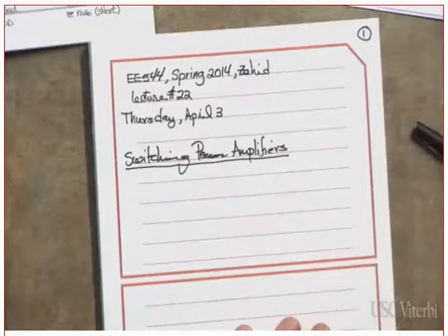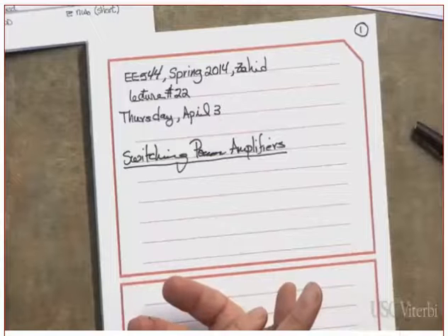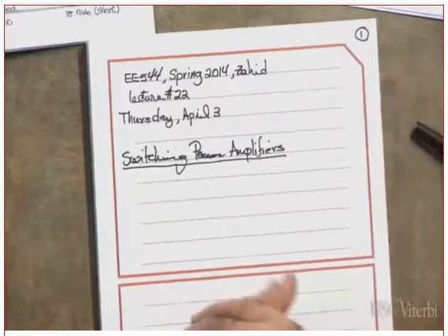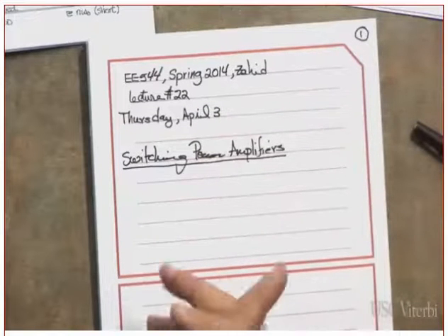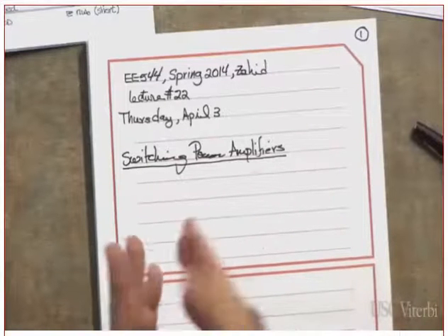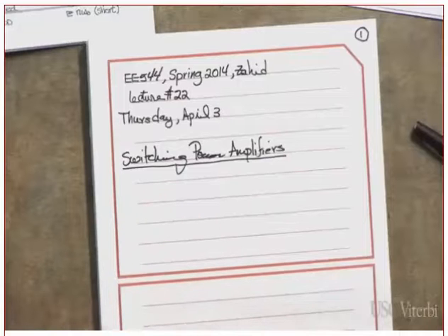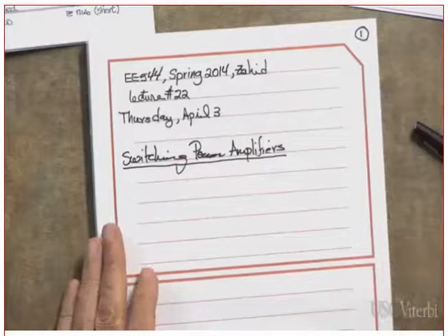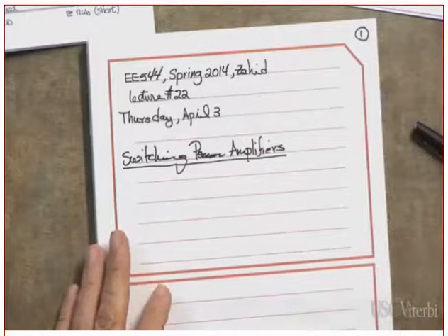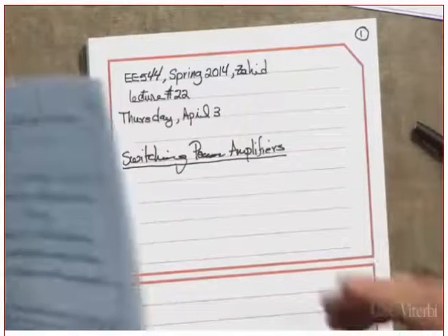Why? Because if you create a square wave and you expand it in a Fourier series expansion, you will see that the fundamental will go higher than the peak value of the square wave. It will go a little bit higher. Clear? It's the ratio of 4 over pi, which is a little bit higher than 1. Clear?